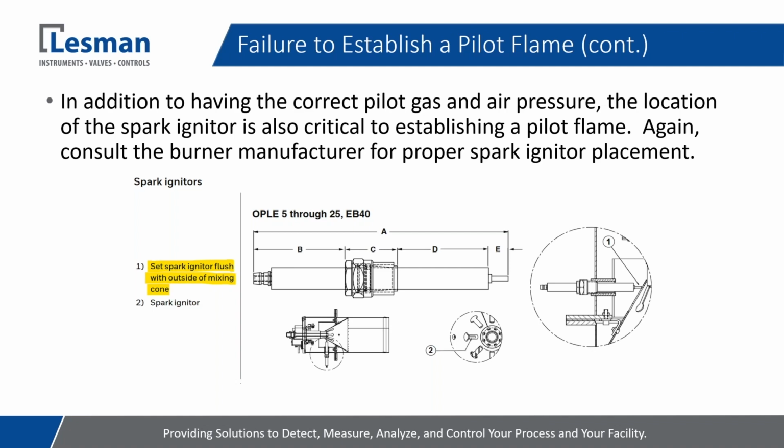So it's very critical that we get the positioning of this spark igniter properly. And with good solid burner design, there usually is a little bit of flexibility with it. But I always like to go off of the literature and set that exactly to where it needs to be. I know that they have done numerous tests on the equipment to know where that spark should be located. And again, the literature will dictate and show you.